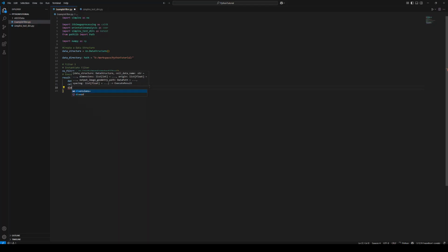This step defines the base image geometry by setting the geometry name, cell data name, dimensions, origin, and voxel spacing, which establishes the physical size, resolution, and coordinate layout of the data domain. These parameters control how all subsequent data arrays are spatially mapped and interpreted inside the pipeline.